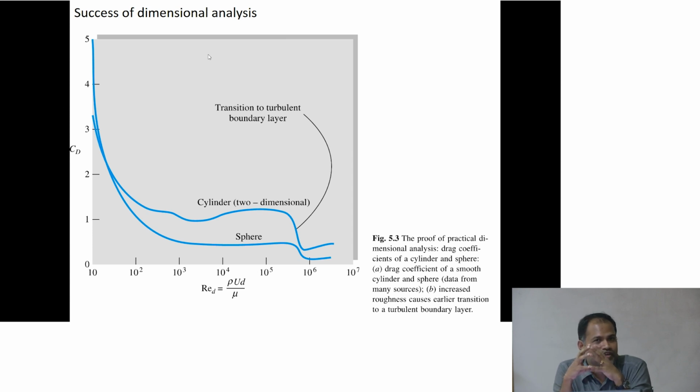Okay, and we know that you can actually calculate the force exerted by that object simply as a function of Reynolds number, and what you see is essentially that graph. Okay, on the left hand side, it's called the drag coefficient. It's the force. It's that drag force that we calculated over rho u square L square, okay, versus Reynolds number. That's how you get this plot, and this is a plot where whatever experimental observation, whatever simulation you do, you can actually put it into a single line.